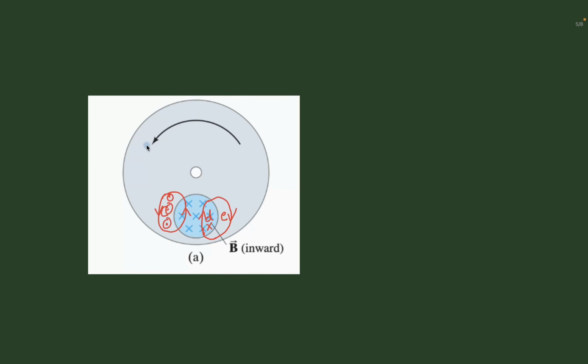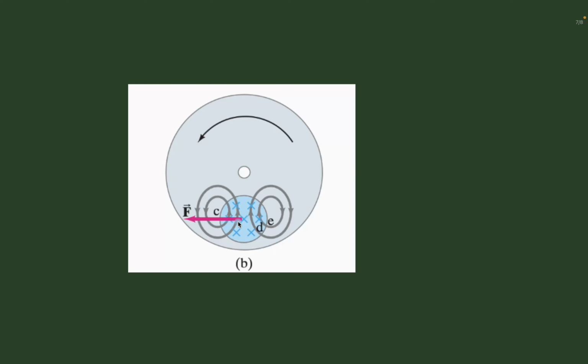So whatever eddy current is generated here, if we look at those eddy currents in those sections, what will happen to them? Let me just remove that. I will make a clear picture here. Look at this. We have anti-clockwise sections of current loops and clockwise sections of current loops in different places, as we have already seen in the previous diagram.